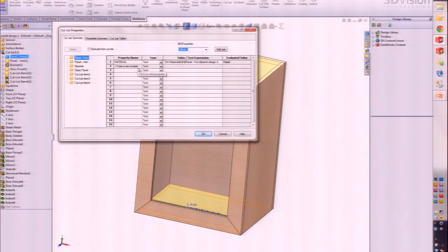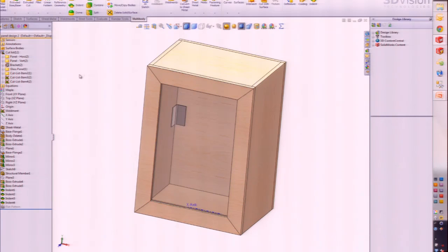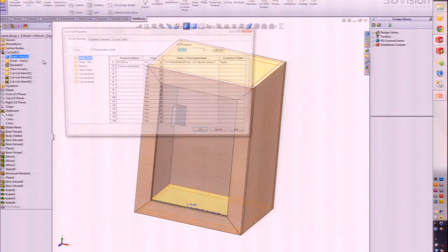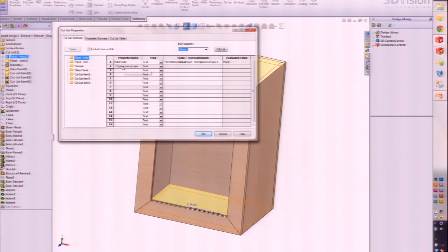No overall size. In 2013, one of my favorite enhancements, because obviously I like multi-body design, comes in if you right-click. What we used to do, just to show you the hard way, is create a length, a width, a height, and then in this field you can click, show your annotations, and click on a dimension, and it will be linked to that dimension. That was a way to do it, but it's very manual, and imagine you're making a huge staircase or something like that. You'd have to do that for every single one.